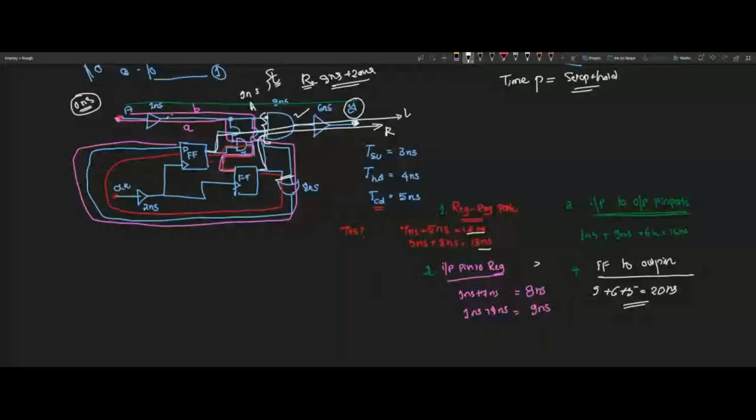how did you compute? Suppose I have the top function, and inside the top function I have some submodules. The first submodule is taking I guess 25 BRAM, the second one is taking 19, the third one is taking 33, the fourth is 36, and the last one is 96. When we add those BRAM numbers, it's giving 209. But the top function is reporting 221.